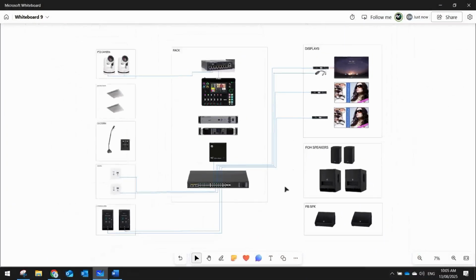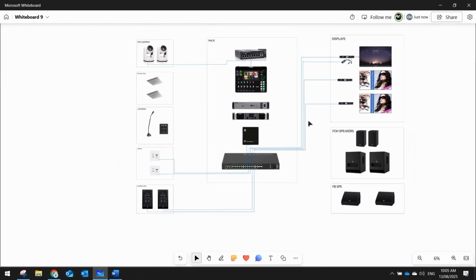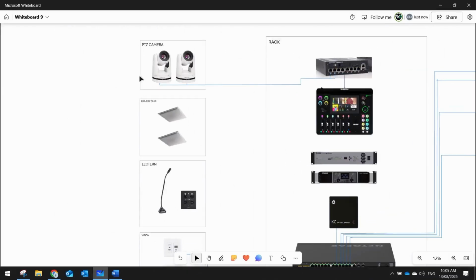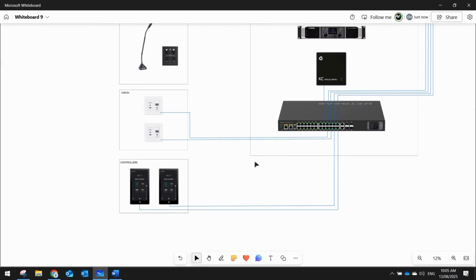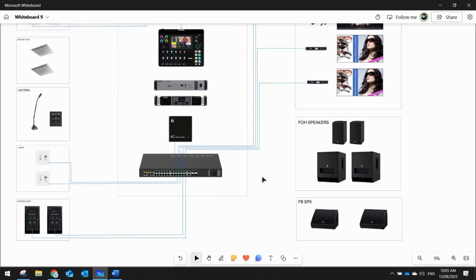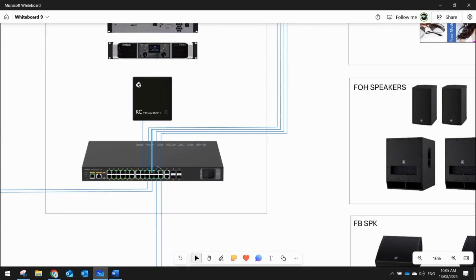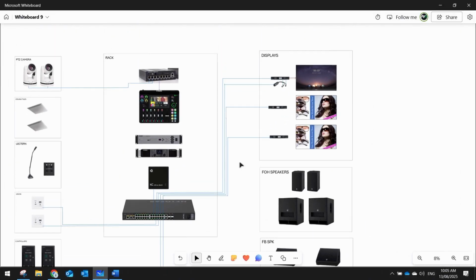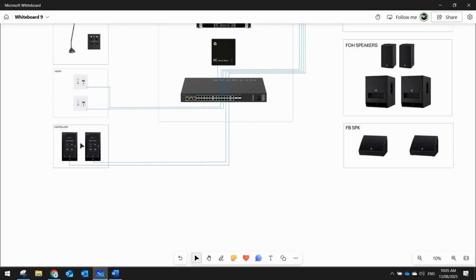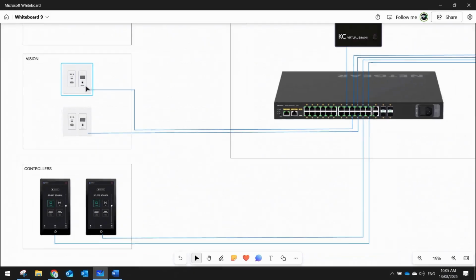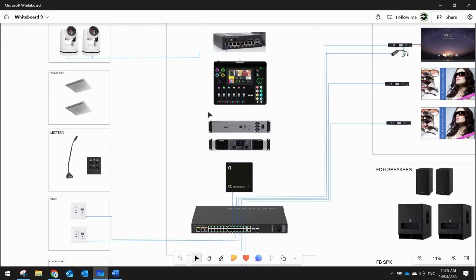Okay, cool. So essentially, I've put all the bits and pieces now in, and I've started cabling up everything. I like to just put everything in boxes with their names, and then I start to work out all the cabling requirements. A lot of this, being an AV over IP system, is all in a network switch, so we communicate with everything via the network. I've started putting all my decoders back. I've started putting my control in, my encoders, so my inputs, HDMI vision inputs. And yeah, we will pick up and continue on from here.